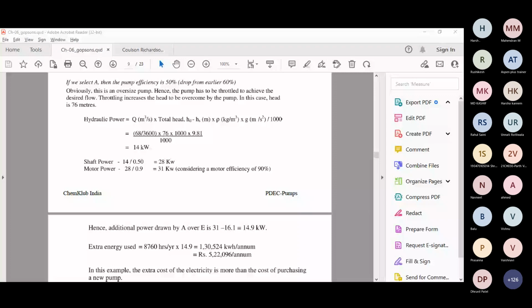Other than this, what you can do is, it is not always useful, the recirculation line is basically a universal solution. Sometimes we are circulating hot oil. When I talk about my particular plant, we circulate hot oil to an exchanger, and that hot oil comes back to the return tank. If I don't require any hot oil, I give one control valve in the supply and another control valve in the bypass line. Whenever my temperature has reached in the exchanger,